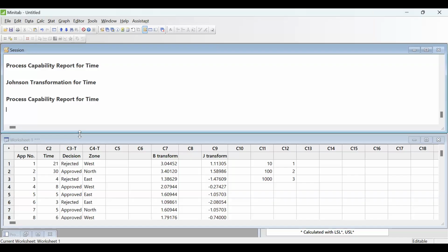So for the same situation, if I have normal data, then my CP and CPK will be more realistic. You agree? Agree, sir. Now, either you should have perfectly normal data or you should not use the bell curve method. If you don't want to use the bell curve method, go to some other curve. There are many other distributions, isn't it? One thing is you find out the equivalent distribution.